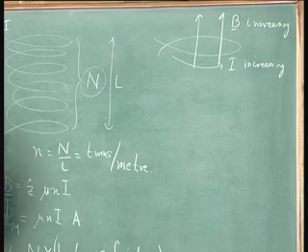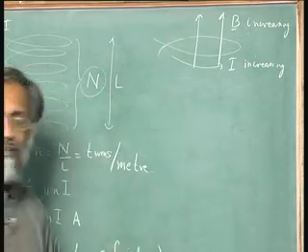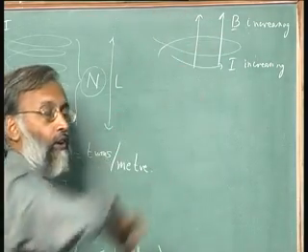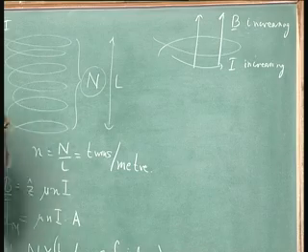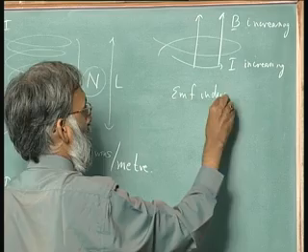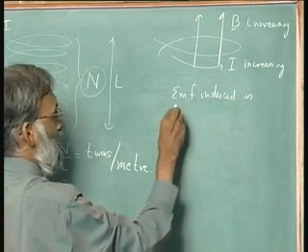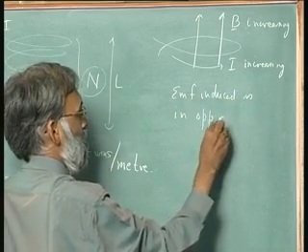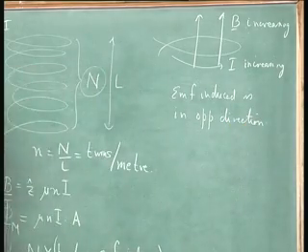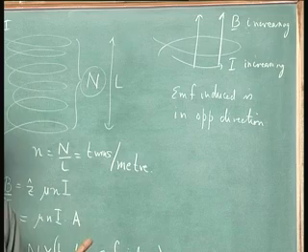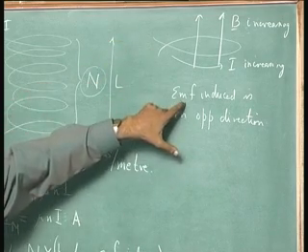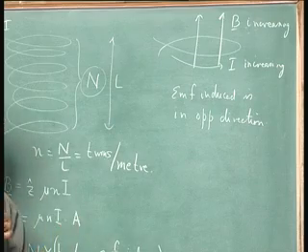The direction of the EMF is so that a negative B will be produced. So, the EMF is trying to drive a current in the opposite direction. So, the EMF induced is in opposite direction. So, it is like a resistance, it tries to prevent this current from increasing. How does it try to prevent it? It is trying to put a voltage that is trying to drive current in the opposite direction.